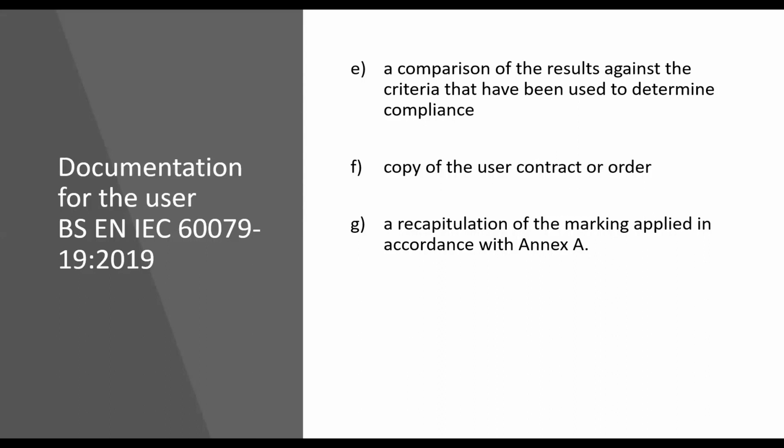Because remember, the user is putting this equipment into a hazardous zone. If the measurement is 0.195, it's very close to the maximum. Again, the agreement between the user and the repairer needs to be in writing, then everybody's covered.